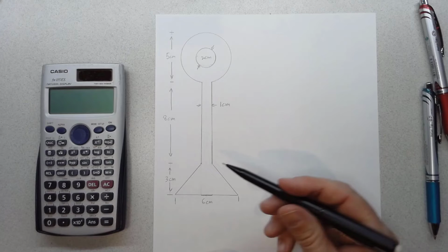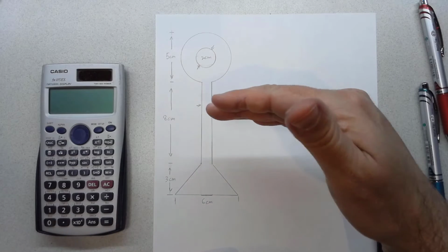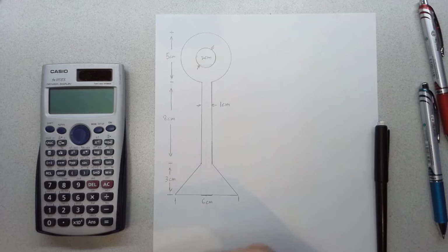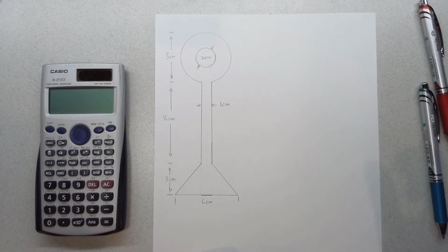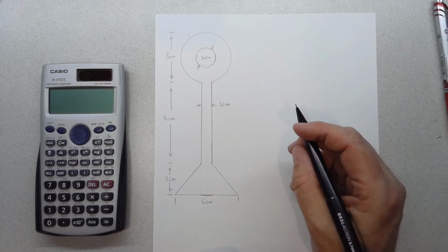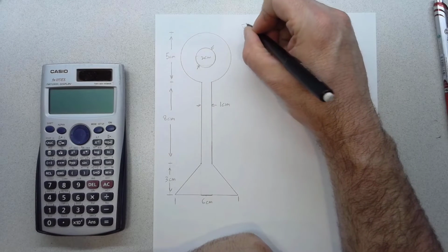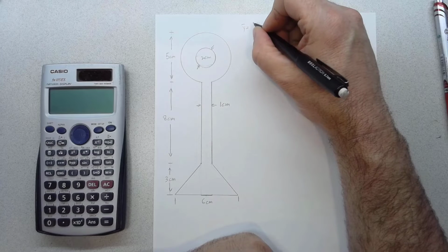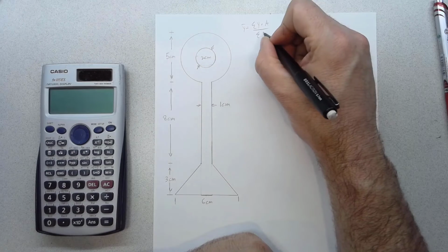So first step, as with any shape that we're trying to find, is we need to find the centroid of the composite shape, because that's where the neutral axis will be. And when we're looking to find I, or moment of inertia, it's always about the neutral axis. So first step of any composite shape when you're looking for I is first you have to find y bar to find the neutral axis of the composite shape. Remember that y bar is equal to the sum of the individual y's times the individual areas, divided by the sum of the areas.